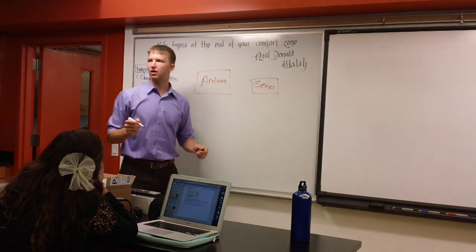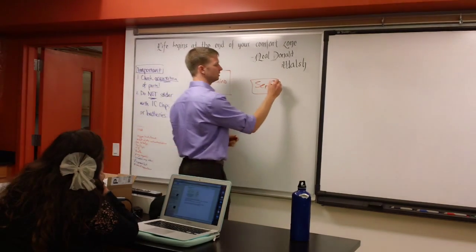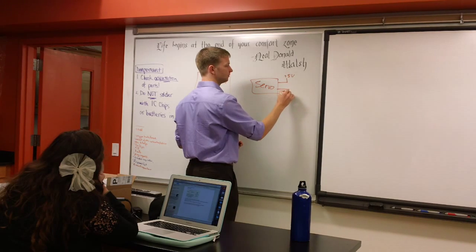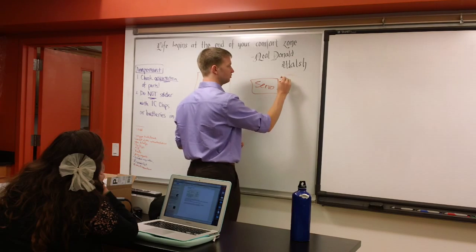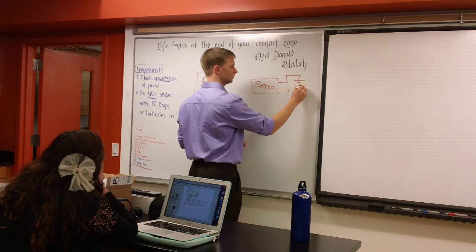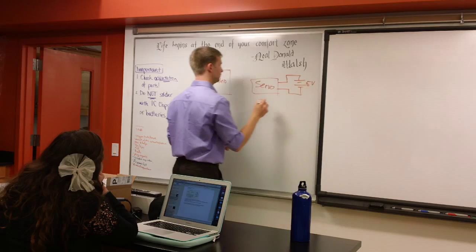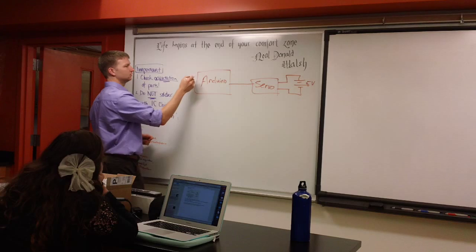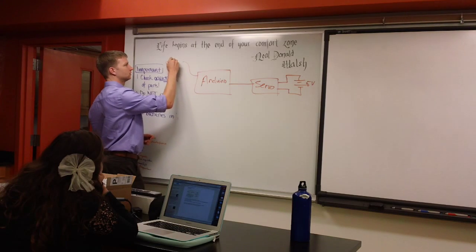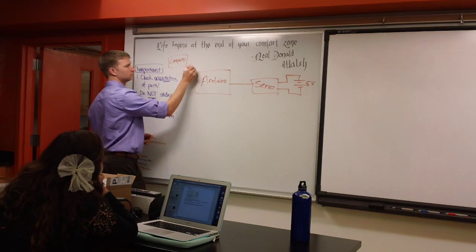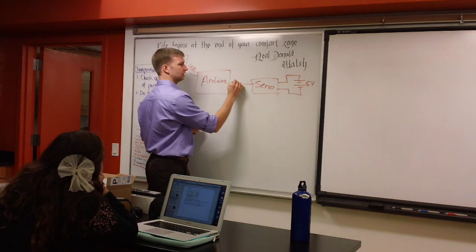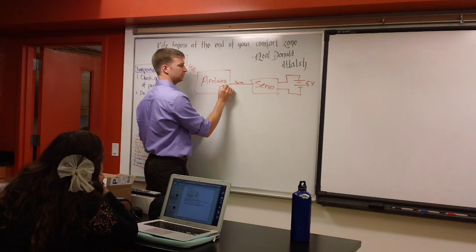For those of you that don't know, if your servo needs a lot of power, you need to give it power separately, plus 5 volts. You need to give it its own battery. And then your Arduino is hooked up to your computer over USB. Does this make sense, everybody? So this is your servo, your data line. This is the I/O pin of your Arduino.